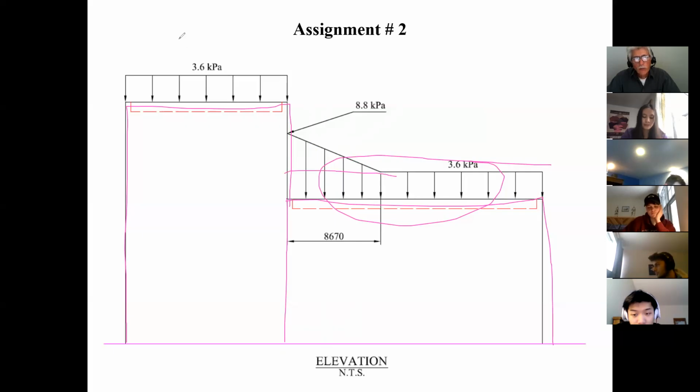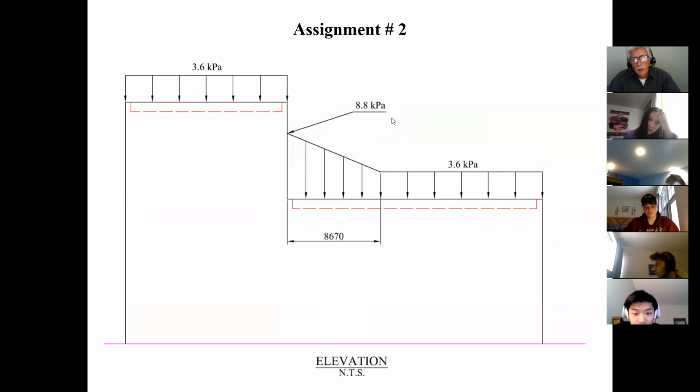And now, in order for him to do this, he has to reinforce this part of the building to account for the possible accumulation there. And that's where most of the problems occur when they make extensions next to adjacent existing buildings, and they're higher. And then the person doesn't want to pay to go and reinforce that part of the building, and that's where the problems occur. So I'd rather you guys be aware of that, and you know what the consequence could be.